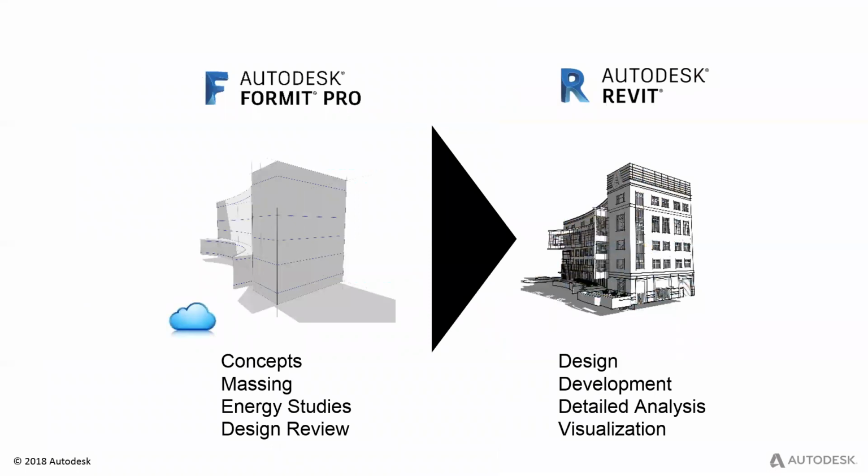So looking at the first kind of tool, you might be looking at an early stage design process and looking at digital sketching tools as well, where you might start your design process and then move that into Revit. So I'm going to focus on something here called Forma Pro, which allows you to sketch conceptual massing and perform energy studies on those at a very early stage.